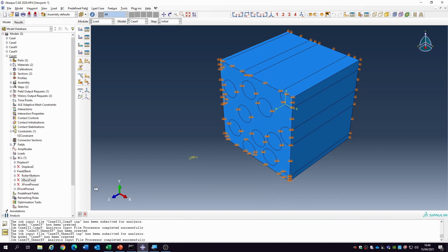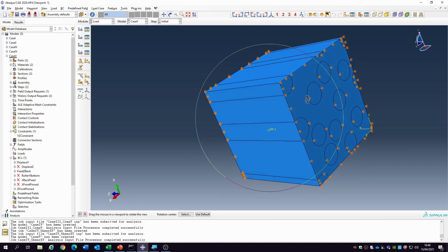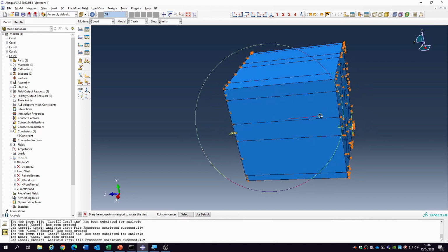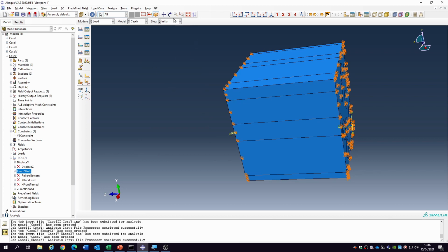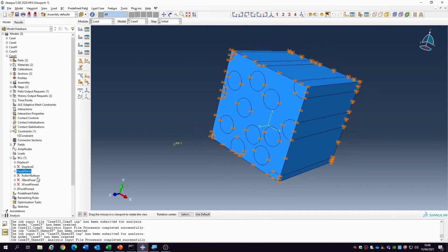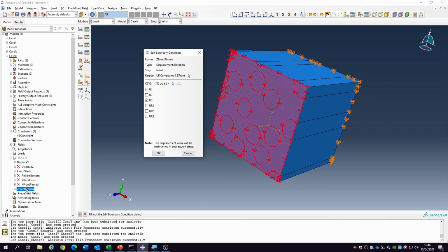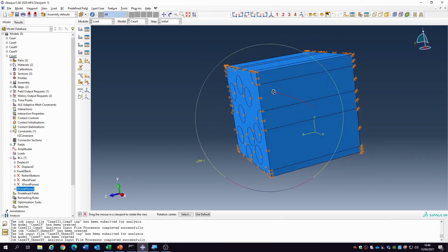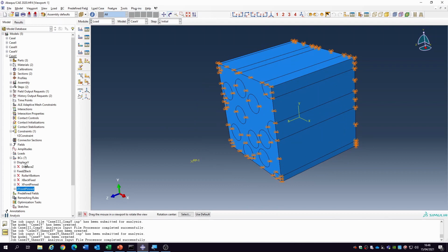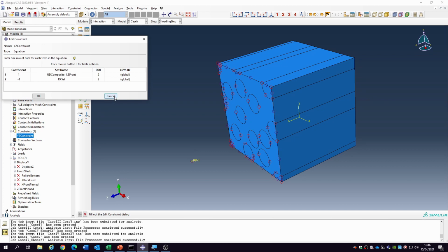All right, so let's just study what we have done. Basically on this beam, on this structure, the back end is securely fixed. Let's make sure this is what we want. Fixed securely at the back in every possible direction. So that's what we want. The Z front is fixed so that degree 2 is the only direction that you're free to move, and this is what we're going to use. And our displacement in the Y direction is there and it's linked to a Y constraint, so everything is fine.